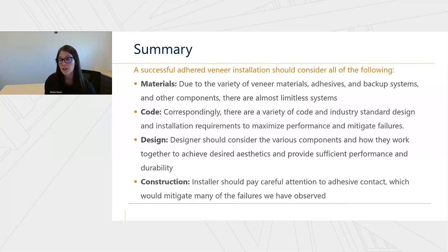Regarding the code, there's also a variety of code and industry standards that are out there for both design and installation, and really having a good understanding of this to both maximize the performance and then also mitigate failures. And then during construction, one thing that we see is installation issues. So making sure the installer pays careful attention to adhesive contact, which is going to mitigate many of the failures that we talked about and also that have been observed in the field.